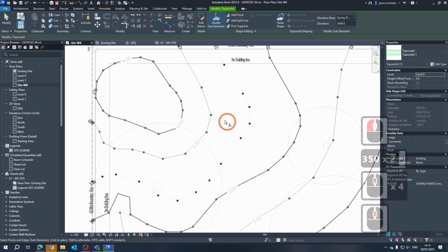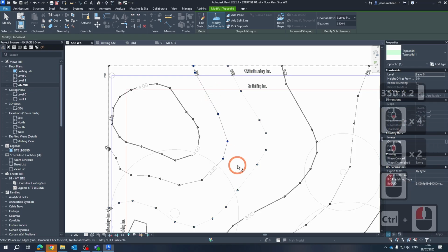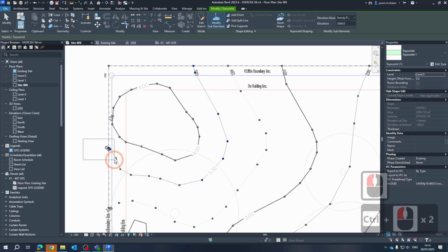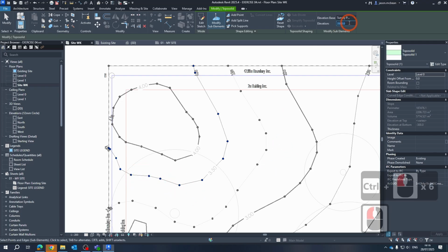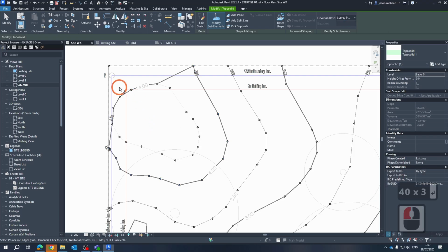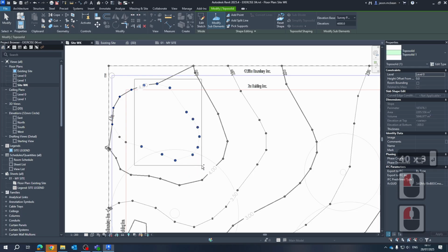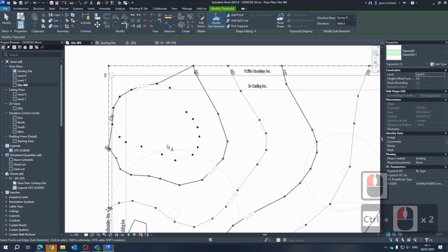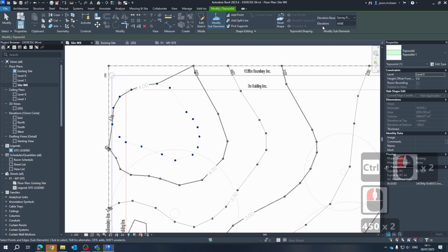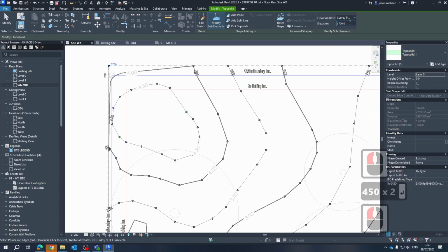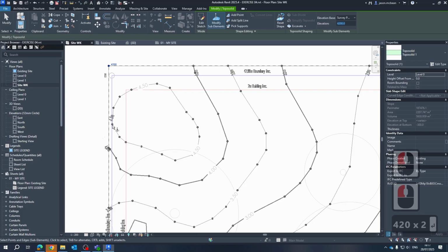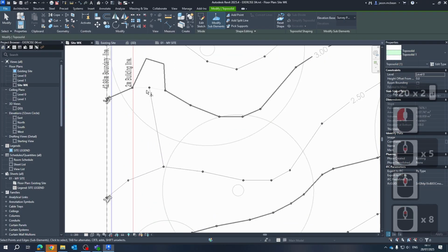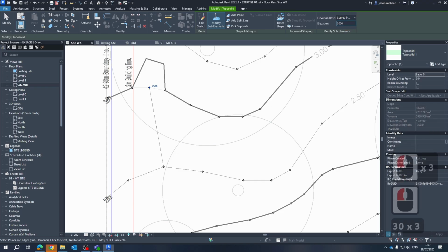We had created a plateau. This will be your 4 meters. You need to select all of these points, by the way. That'll be your 4 meter, 4000. Okay, and then these will be your 4500. That is a bit frustrating. And that'll be our 4200. Okay, so now we fixed our topography. That point didn't quite work, so we probably missed a point there. That should have been 3000.